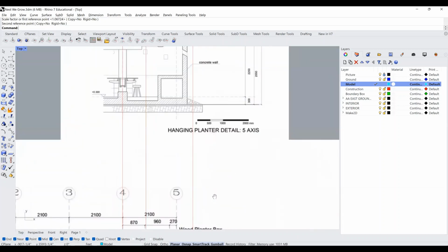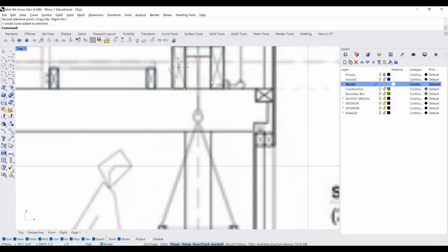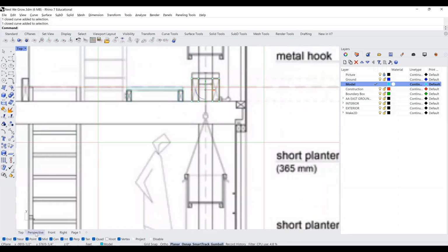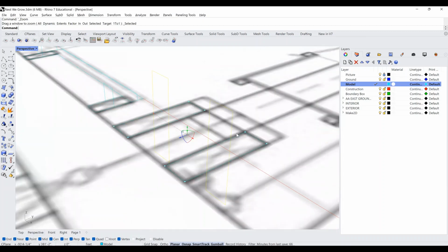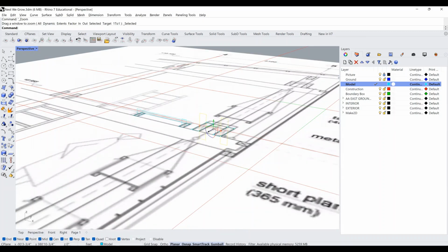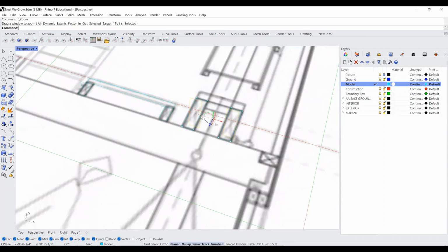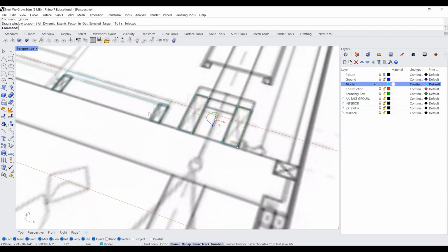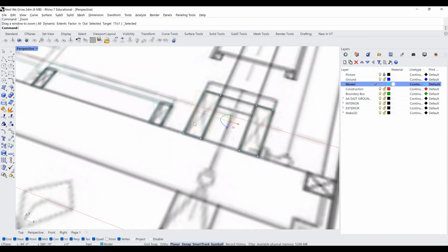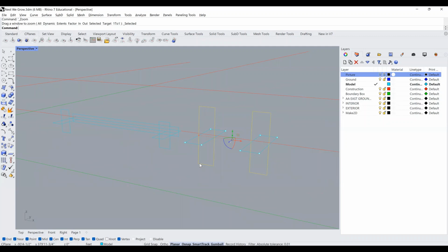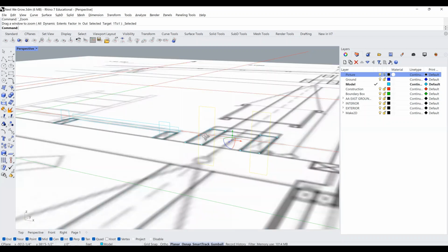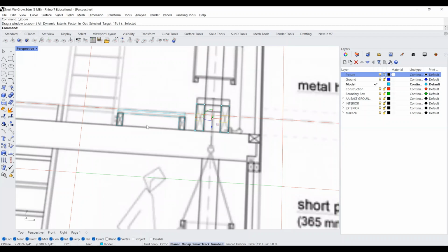So in the same way, I'm going to go ahead and rotate these pieces. And I'm going to go back to perspective actually, and zoom select this again, and let's rotate this 90 degrees. And so one thing to note is that this was rotated about its axis in the middle of the rectangle, if that makes sense, right? And this was rotated about its own middle axis. And so if we turn off this picture, this is then set below this rectangle, this beam, if that makes sense, right? And so we know from the detail drawing that these beams rest at the same height.